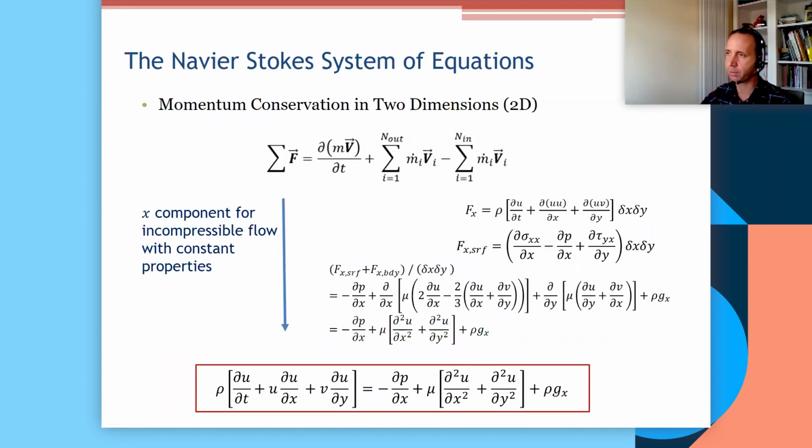Because when you sub that into our momentum conservation equation, we've proven that the force on x is going to lead to a change in velocity, and we now have a way of expressing that force in terms of the stresses, which can then be defined in terms of the velocity gradients. If you sub this definition, you end up with this momentum conservation equation, which relates velocity in the x and y direction with pressure. These come from the shear stresses, and you've got the body force.